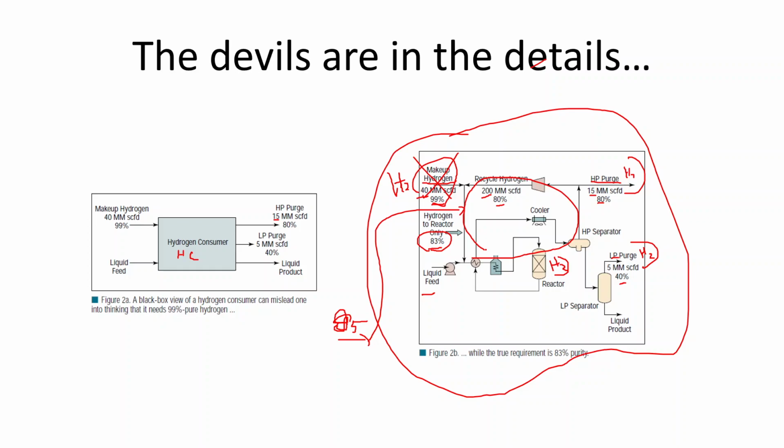So in that case, we have to have a high partial pressure of hydrogen to make sure that the active surface of the catalyst is always cleaned, right? So it always has to have enough hydrogen so that it doesn't crack to become coke. So that's the goal of having a huge hydrogen recycle.